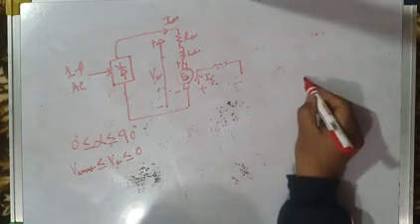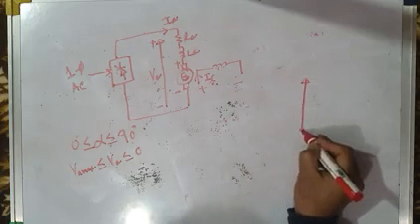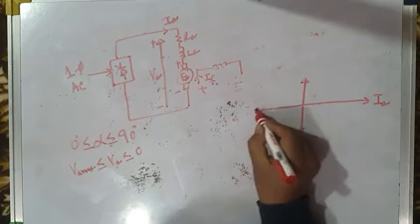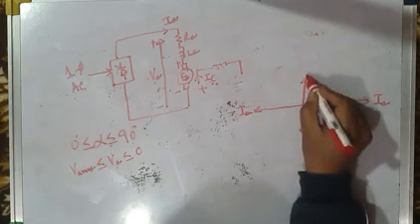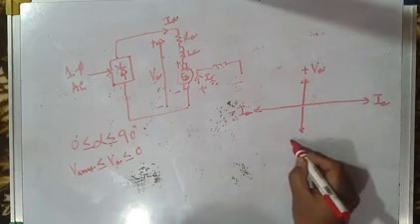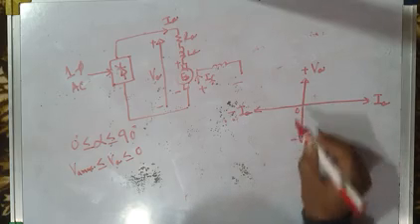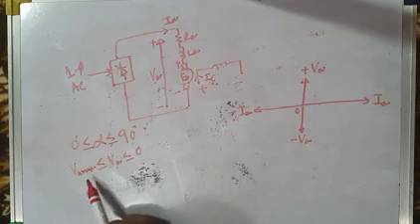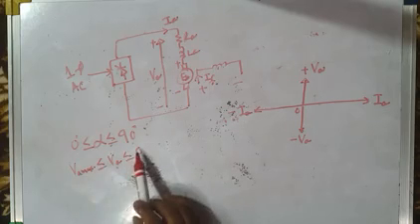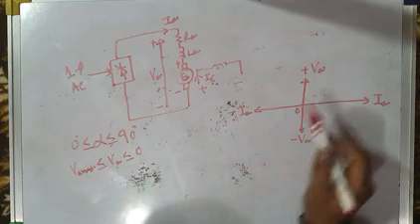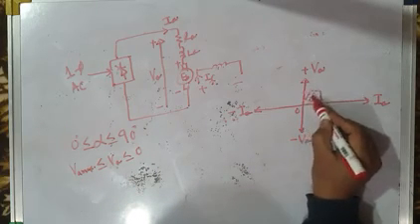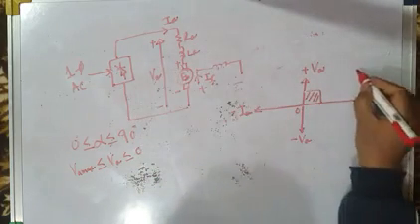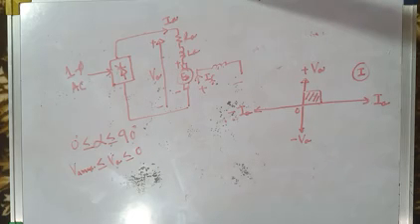So if you look at the quadrant operation, say for example, this is positive armature current, IA. This is negative armature current, minus IA. This is positive average output voltage, VA. This is negative average output voltage, minus VA. For delay angle varying from 0 to 90 degrees, you get average output voltage varying from 0 to Va max, but it is always positive. So your DC motor drive operates in the first quadrant of voltage and current.